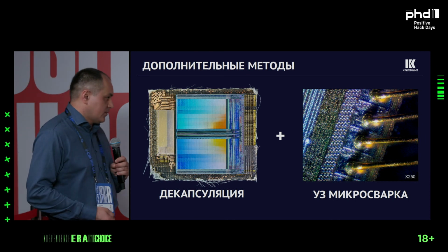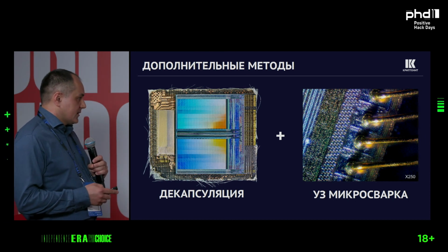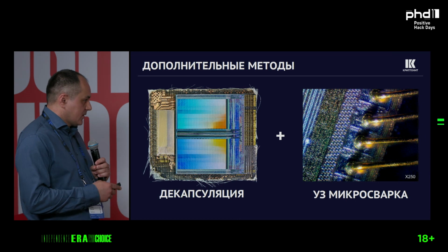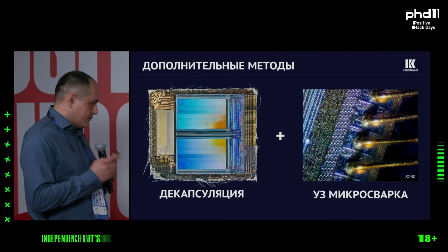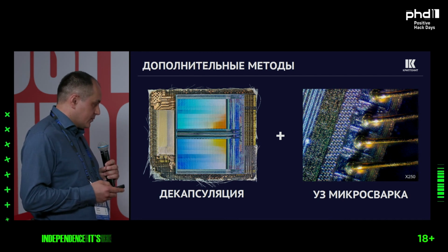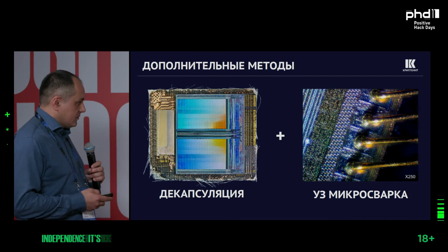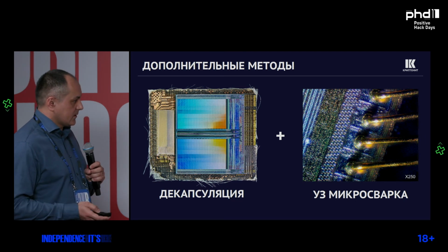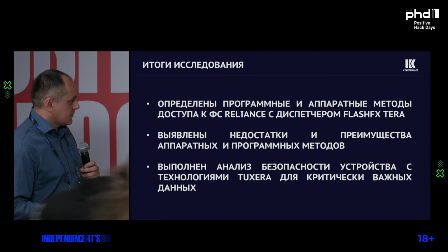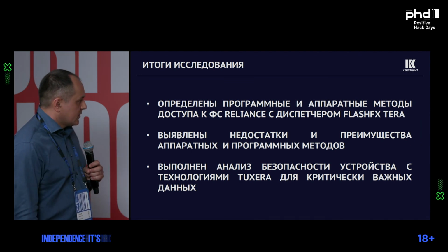and we can also remove the case from the chip using plasma chemical methods. Then we actually solder the contacts to the chip, even if the controller did not allow us to access those areas.